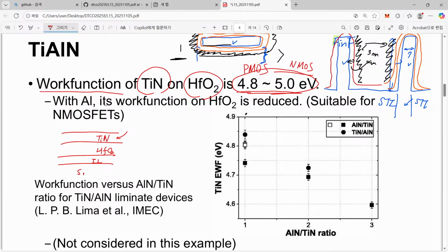Why is it perfect for one and not good for the other? Because we always want to have a certain value of threshold voltage. More or less, nowadays threshold voltage is given as 0.2 something. Anyway, the absolute threshold voltage for a MOSFET should be higher than 0, and not too high, not too low. So in that case, this value is not good for an N MOSFET.